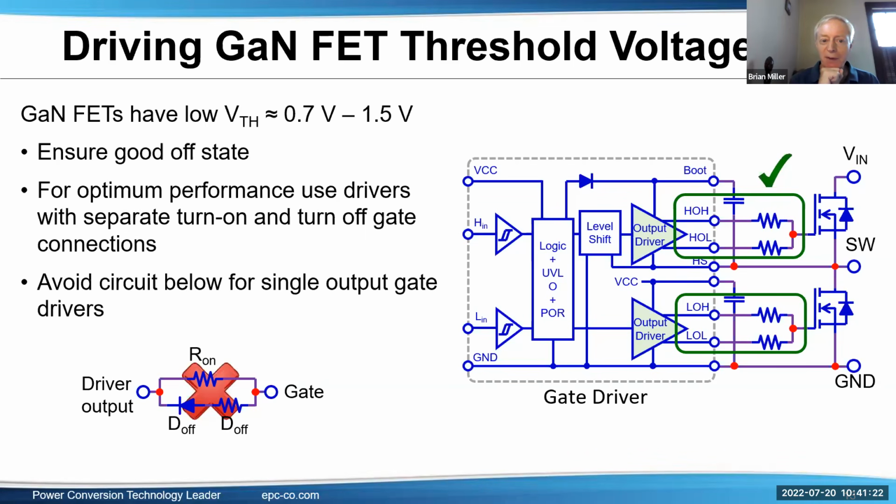I'm not sure I'm answering this very well, but whoever asked the question, if you want to contact me directly, that'd be great. I think you're saying for inrush, for example with a load switch that switches in, you'd rather not have so much current. Either through current sensing or through the gate drive itself. But again, putting a resistor or a capacitor from this point, from the drain down to the gate, you might be on the wrong side of the Miller capacitance and actually cause it to unintendedly turn on under fast switching.